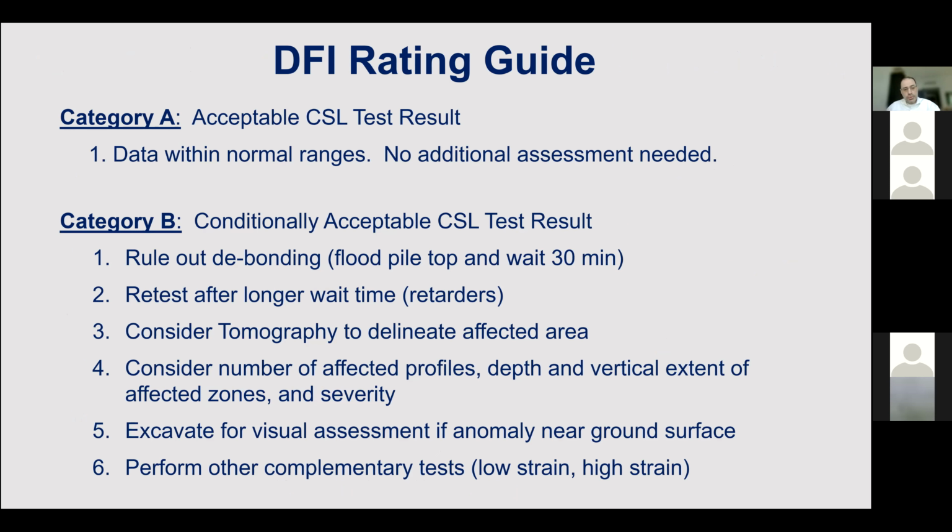If you want to consider more advanced analysis like tomography to delineate the affected areas, you can definitely do that. So you can consider the number of affected profiles, the depth, the vertical extent, and then you assess the severity. If it's possible, you can excavate for visual assessment if it's near the ground surface, or you can do complementary tests.